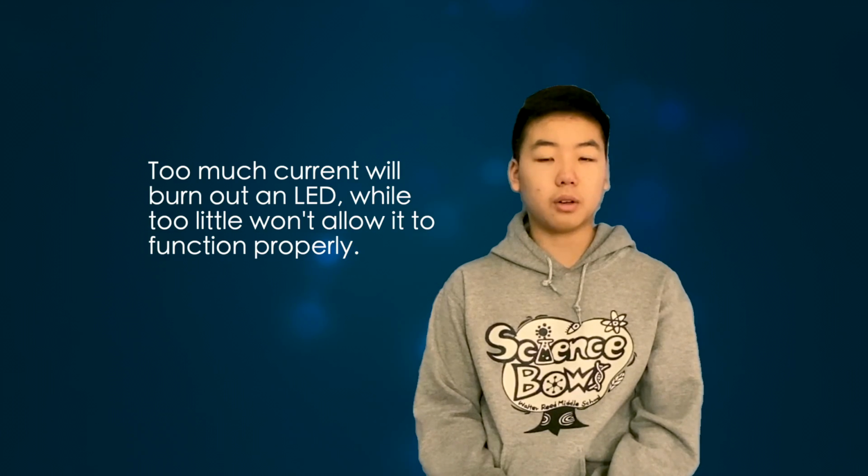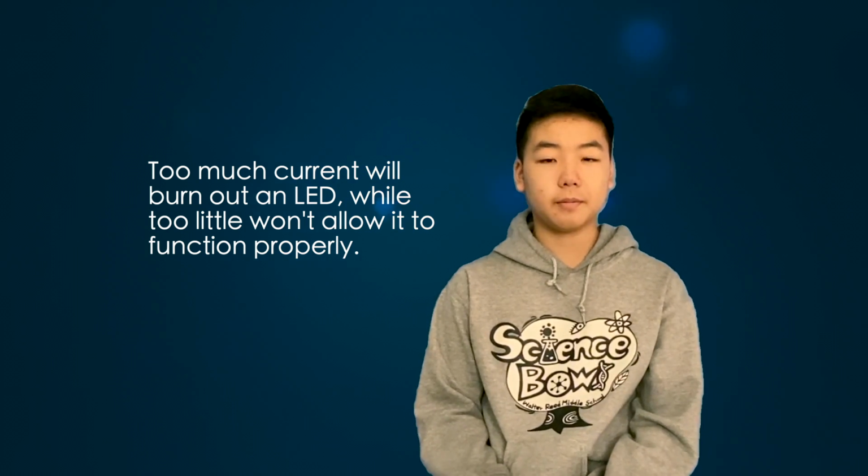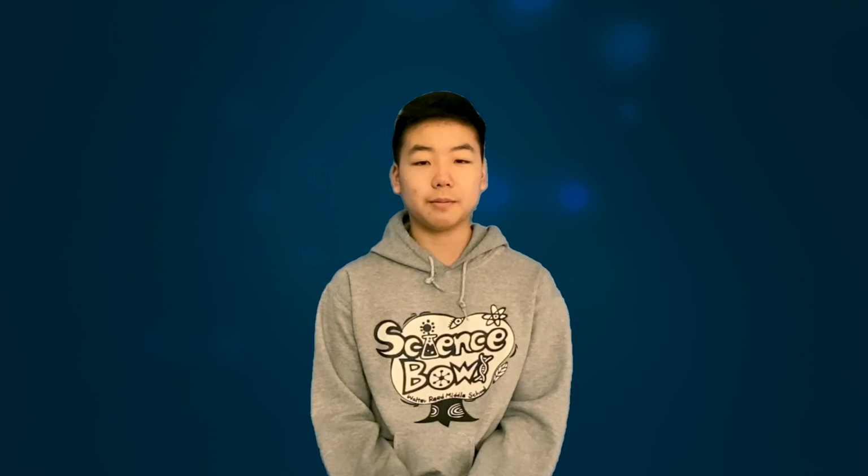Although resistance blocks the flow of current, it's not always a bad thing. For example, a resistor could be used with a sensitive component such as an LED. You don't want too much current flowing through it or else it will burn it out. But you don't want too little current because then the LED won't function properly. A resistor would allow you to control the current and tune it so that you get just the right amount. A resistor is one of the most versatile circuit components, and this is just one of its many uses.